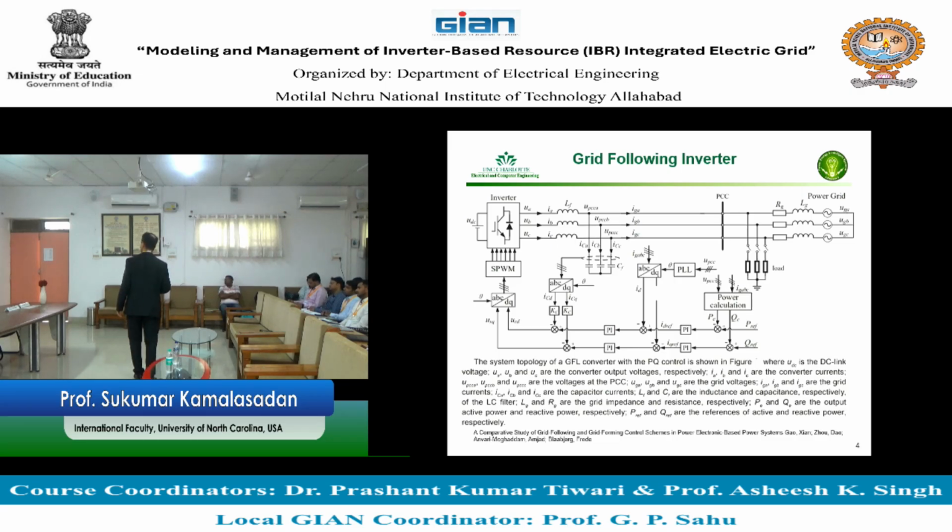So here you will see that the current reference goes to another PI, based on the current input right here, and then generates the voltage signals out of it. So you have one controller here, another controller here. These two controllers work together to convert the power to current to voltage, and then you give the inductor the output value for the voltage, right? So that is called cascaded operation.